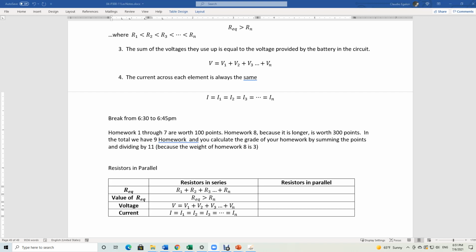If I want to accommodate a third resistor in parallel, I have to make more room here, right? This wire here is all twisted. I connect on the same row. Here you go. Three resistors in parallel. And now I can connect my power supply to those two ends. Here you go. My battery here and here.